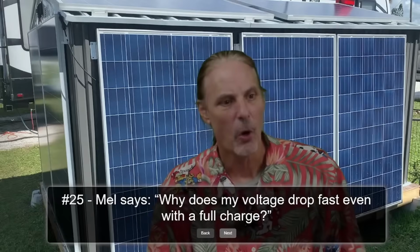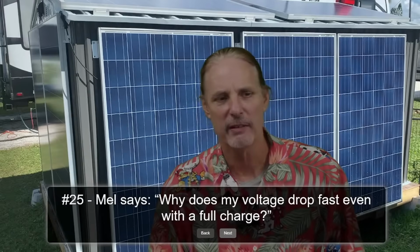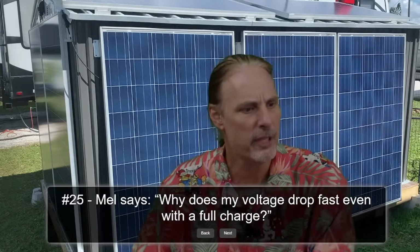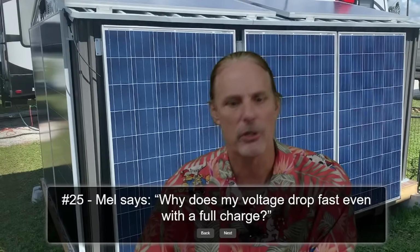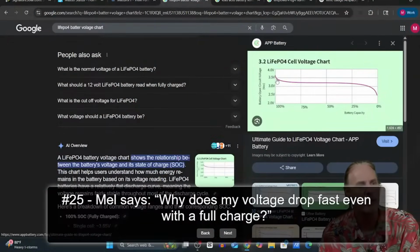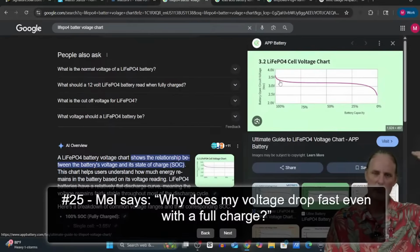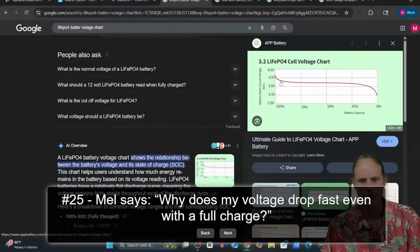Mel says, why does my voltage drop fast even with a full charge? And my question would be: is your voltage drop what you're seeing? Let's see if I've got that chart here still. I do. So that would probably be this drop here. When your battery is fully charged, lithium iron phosphate goes up to 3.6. But as soon as you start to use that battery, it is going to drop quickly down to 3.3, 3.2, and get to this point right here within this chart. And then it's going to hold steady there.